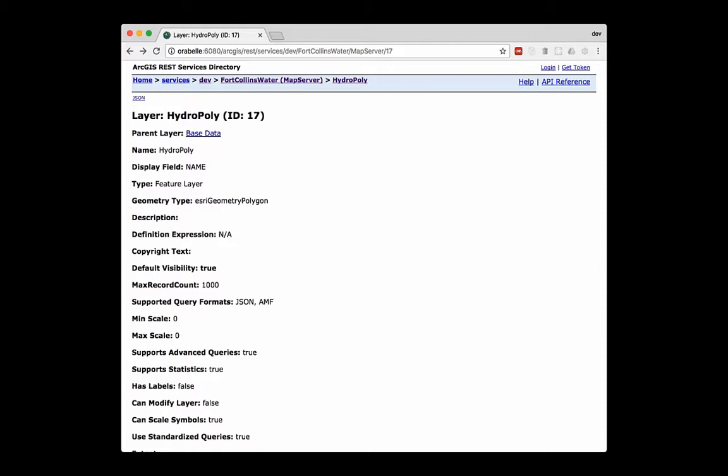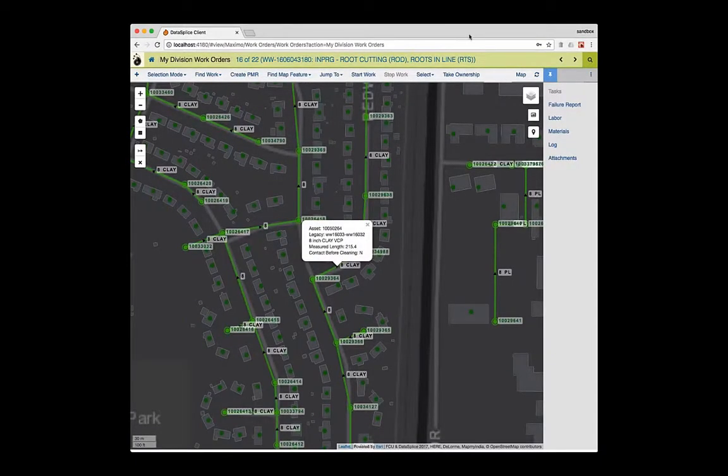The same thing goes if we were talking about features in a city. So we're looking here, and you can see lot lines and premises and pipes and manholes and flow direction arrows. It might be that each of those has multiple attributes on it. A manhole might have multiple attributes such as radius and type, wastewater versus stormwater, and other attributes. But one of those attributes could be the region or the zone that it's in. And so if such an attribute exists, then we can use that to our advantage and say, hey, only fetch the features that belong to this zone because we know that these users are working in this zone.